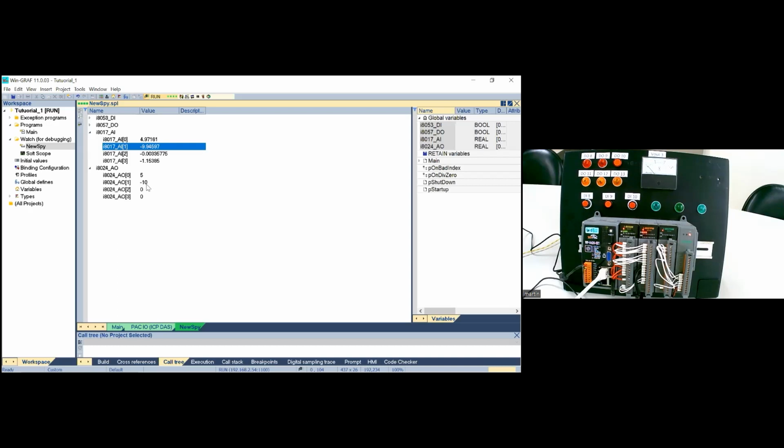the output setting is correct, and the 3rd output channel is directly connected to the voltmeter. We will set an output voltage of 5, and you can see the voltmeter is set to 5. So the output setting is correct. This is a convenient way to individually test each channel and check whether the connected devices, such as sensors or switches or gauges, are correct.